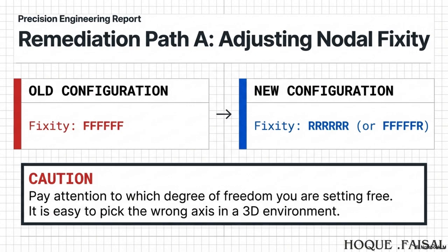And this is where the software really does its magic. It runs what's called a linear static analysis. It just means it's doing the math. Right. It crunches the numbers on the weight of the steel itself, which is about 0.706 kips, so 700 pounds or so. Yep. And it calculates the force of that 81 mile per hour wind pushing on it. And then it spits out the results. The perfect result. I'm looking at the displacements table right now. This table tells us how much the wall actually moves when that huge wind hits it.